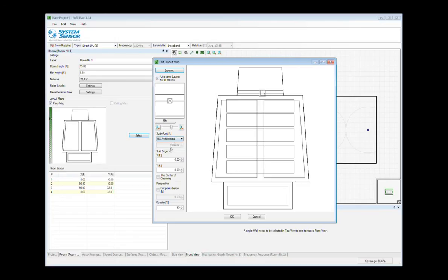And so the scaling factor between meters, which is what our raw data format is, and feet and inches is actually a scaling factor of 0.08333. Now, if I were working in meters, it's more commonly that I would get a drawing from AutoCAD that was either in millimeters or meters.